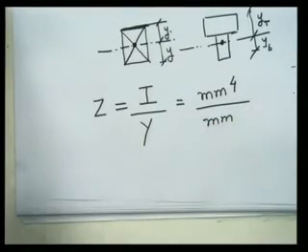Now tell me one thing, how do you locate neutral axis? The neutral axis is located by finding out the centroid of the section. If you go through all the numericals that we have solved, we have found out the CG of the section, and from that particular CG point, the line is passing, and that line is nothing but the neutral axis. So to locate neutral axis, we have to calculate the CG or the centroid of the section.